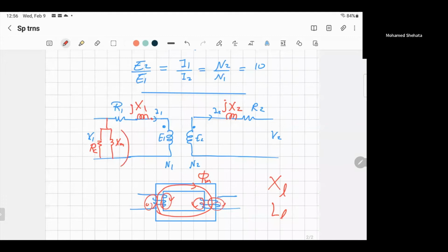So this branch is used when you want to include no load loss. It means if you don't have load here, you will find loss here. Of course, when you add load, you'll have many more losses, and this one is still there, but it does not depend on the existence of load. So that's the whole equivalent circuit, and we're going to go into detail.